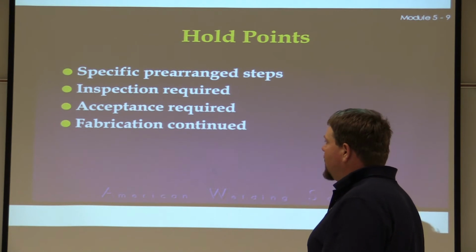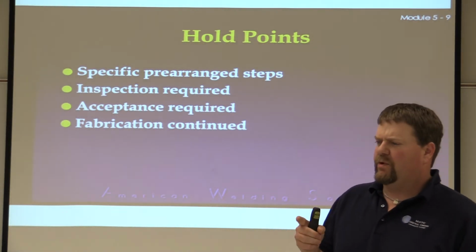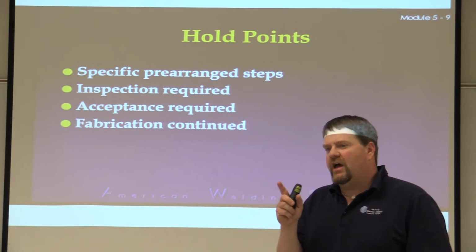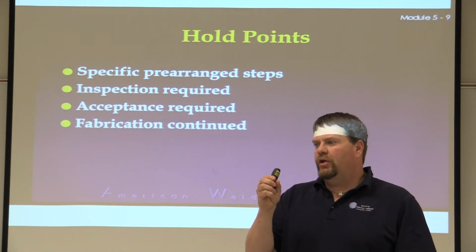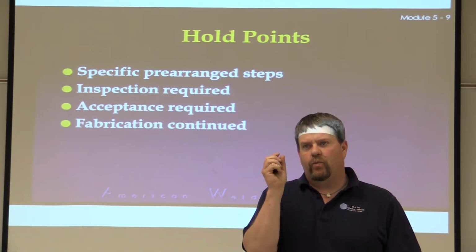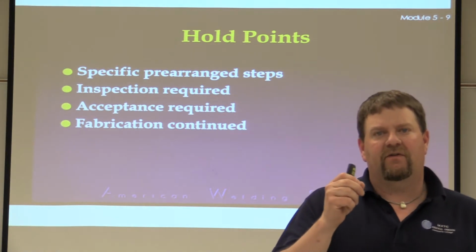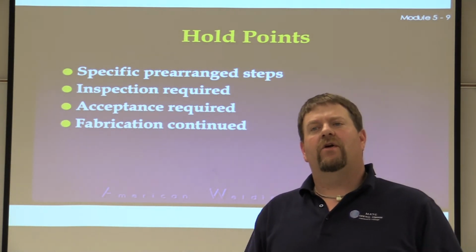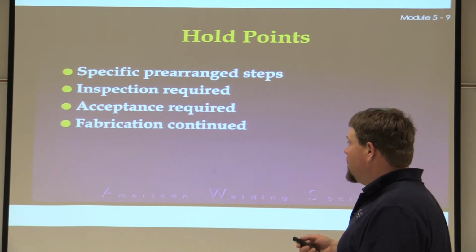Inspection required. Sometimes the inspection is done as a fit-up. Inspected and require a 3-part piece. Number one is as fit-up usually. When we get into the print, it'll tell you, your root opening is supposed to be 1/4 of an inch, as fit plus or minus 1/16. So you can go a 1/16 below or a 1/16 above, and that's now your tolerance as fit instead of just on the print. Okay, that's an inspection point.